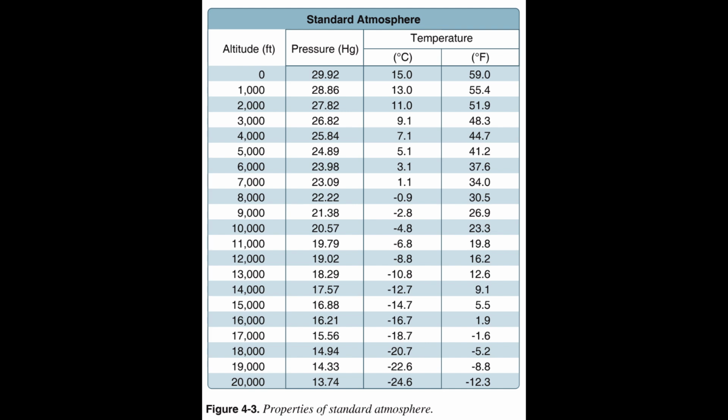The International Civil Aviation Organization, ICAO, has established this as a worldwide standard, and it is often referred to as International Standard Atmosphere, ISA, or ICAO Standard Atmosphere. Any temperature or pressure that differs from the standard lapse rates is considered non-standard temperature and pressure.